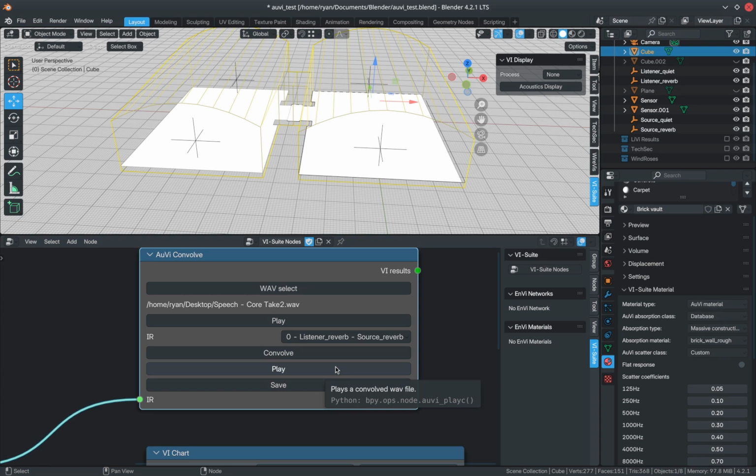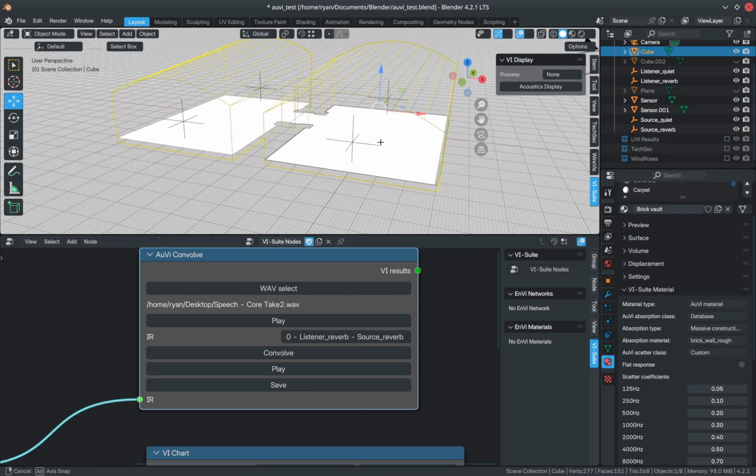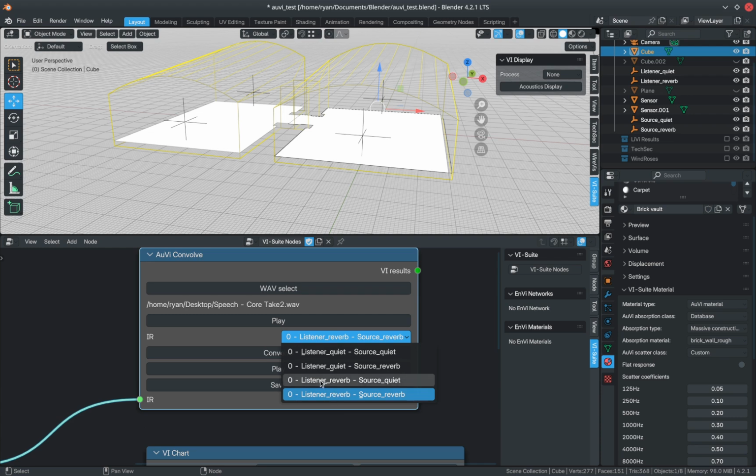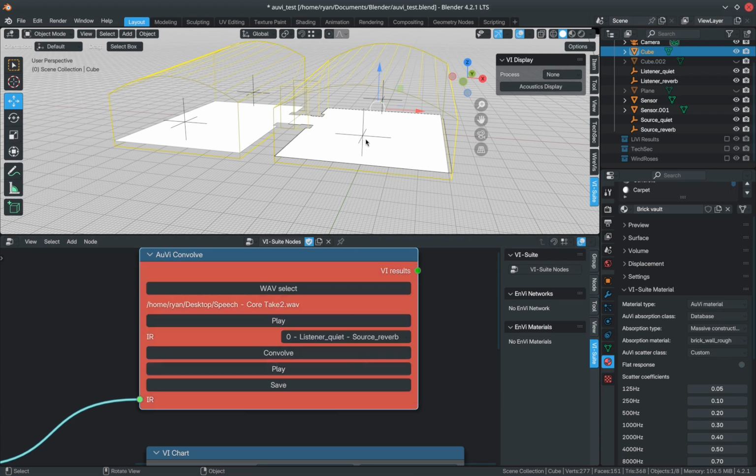So I think it's pretty clear now that we're getting the additional echo, the additional reverberation from this space, which has concrete walls, rather than this space, which has plywood sound absorbing walls. So that, I think, is a really nice way to experience acoustically the space that you're designing. We could have played the sound here and listened to it here.